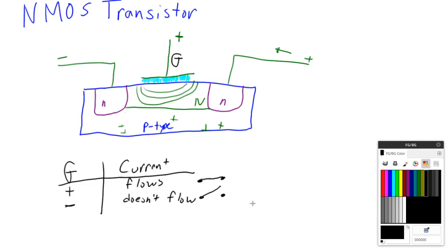And so we could actually look at this as infinite ohms when it's open. We look at it as 0 ohms when it's closed. Of course, it's not actually 0 ohms, but it's close enough for what we need to do in terms of digital circuits. So this is the kind of really crash course of what an NMOS transistor is. You can get way more into what goes on inside these transistors. But the real thing is this table right here. This is the important part.